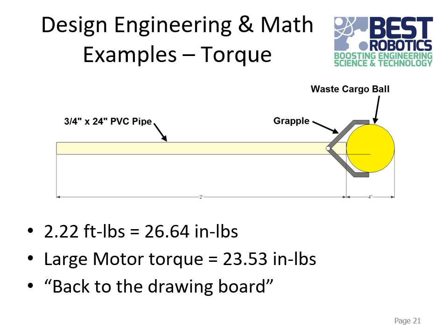So in this case, it would be back to the drawing board. Can we come up with a different design? Maybe you can make it shorter so that it doesn't need to lift as much, like out as far away from it. That'll reduce your torque. Maybe there's something you could do to make your gripper lighter, or make the PVC pipe lighter by drilling a few holes in it. But then you have to make sure that you're not going to jeopardize the structural integrity of it.